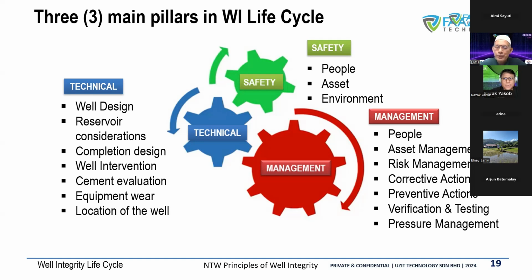In other words, it's subject to condition. If the well starts to flow, then of course hydrostatic is going to be almost like our tool to stop the flowing of hydrocarbon. But if we are dealing with losses, then we're talking about loss of hydrostatic, and the losses will be our concern. Because we are talking about having better control, and we always have another weak point at the bottom, hydrostatic has to always be on our side, so we don't lose the hydrostatic because of losses alone. We should be able to top up the hydrostatic and try spotting LCM and so on to reduce the losses. But if the losses continue, then your hydrostatic barrier does not become a secondary barrier anymore. So your temporary barrier has actually failed.